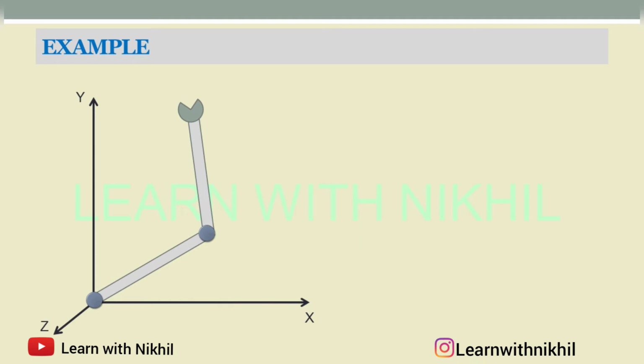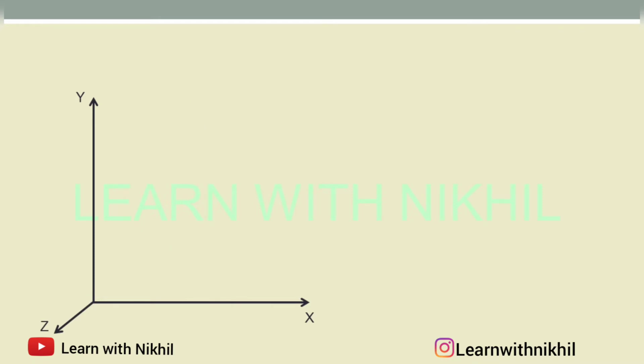Now according to this, using the DH parameters, we will find the position of this end effector. For that, first we have to find the DH parameters. Now we'll build this robot. This is the first joint, and this is the first link. The length of this link is denoted as L1.